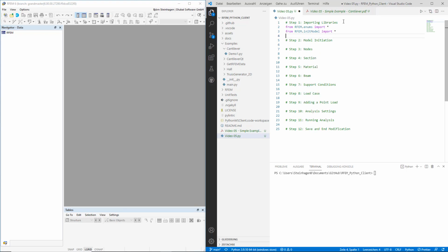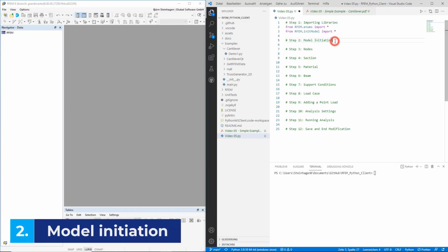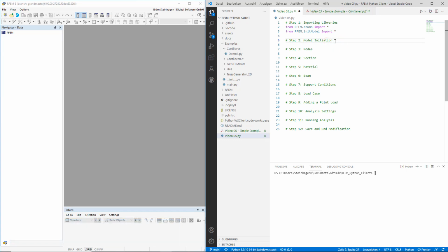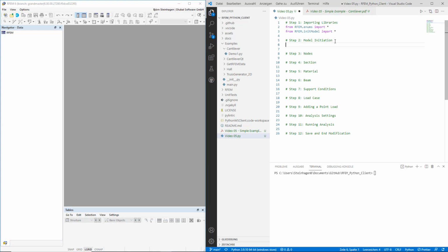Note that when importing a library, the code inside these .py files is actually run, so simply by importing the initModel, some communication with RFEM 6 is already taking place. How we think when modeling a structure in RFEM versus programming it in Python is relatively similar, and with this notion, hopefully the process is cleared up slightly.